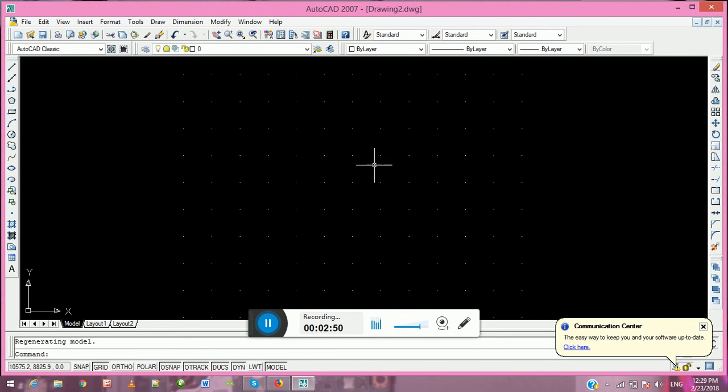You can see now this is the exact place I want to work, and this is the first side, which is 0 by 0 when I was selecting the drawing limit, and this other point is 20,000 by 15,000. So the horizontal is 20,000 in length, the vertical is 15,000. This is what I did when I was choosing the drawing limits. So this is my workspace. This is where I'm going to draw the floor plan.